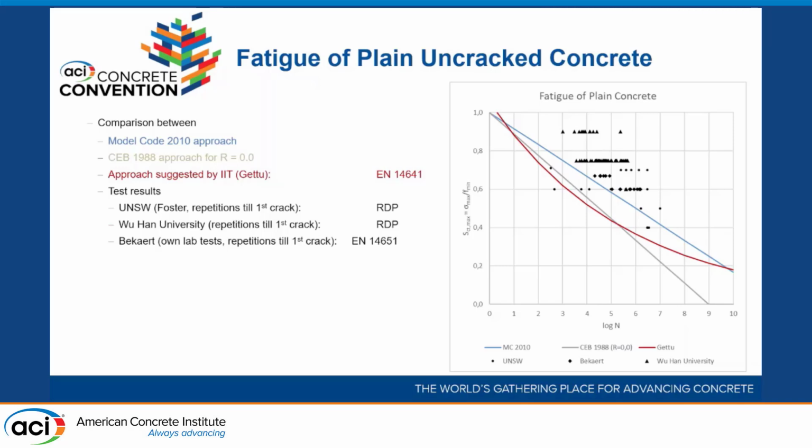But this methodology assumes uncracked first, goes through, and can predict the number of cycles in conjunction with a certain stress level to the first fatigue crack. And then after the concrete cracks, we switch models, and then we can predict the total number of cycles at given service levels, or inversely, service levels given a number of required cycles for the slab on grade. So you can see it's based on this one here primarily, and then our own lab tests. It's also backed up by some full-scale tests.